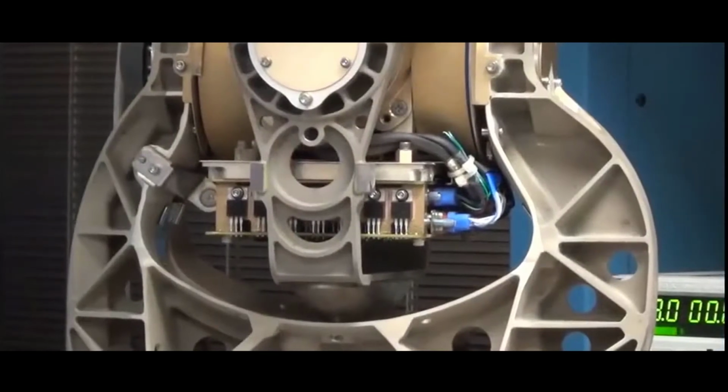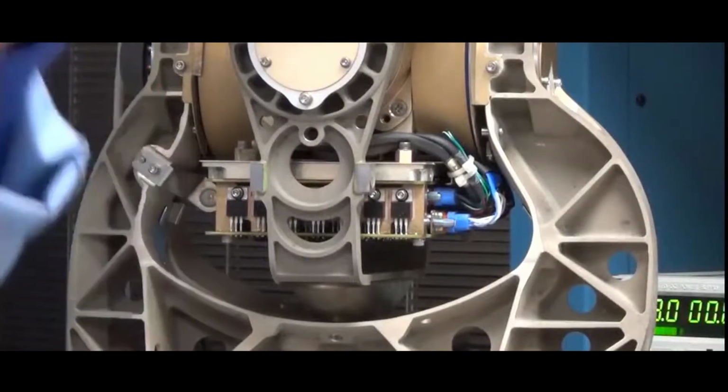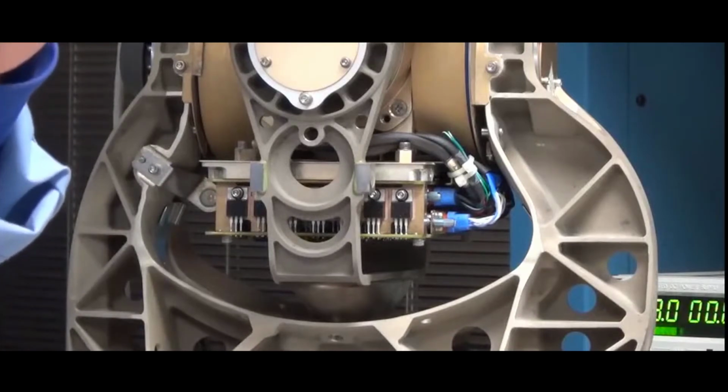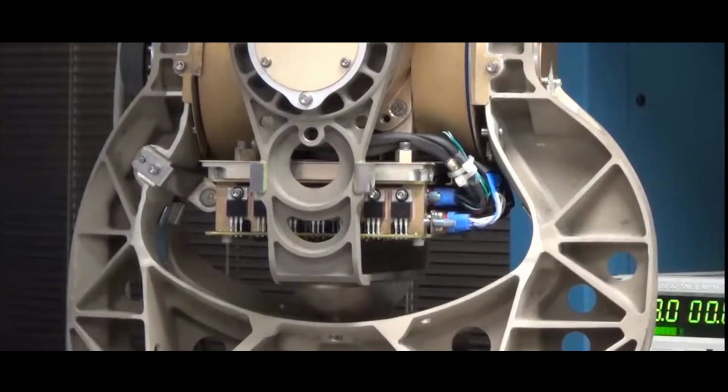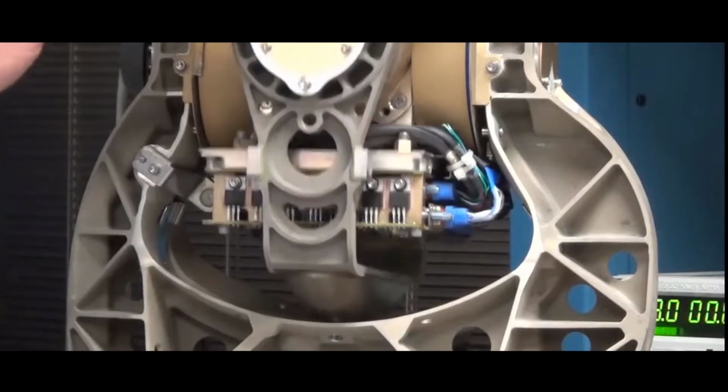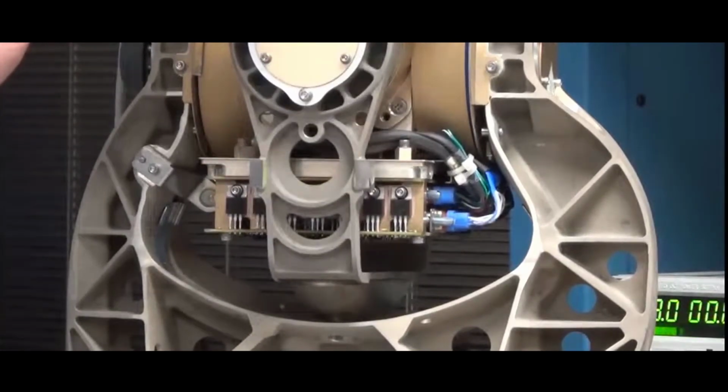We're going to take a non-conductive stick or some type of object that doesn't have a sharp point on it, so we do not damage the equipment, and gently manipulate the wires and the rubber stop and the end of the connectors. And if you see the antenna gimbal move off the center on its own, not from pushing it, you're losing one of your resolver signals. There's a break in the connection, and that's also an indication that you have a bad resolver pin.